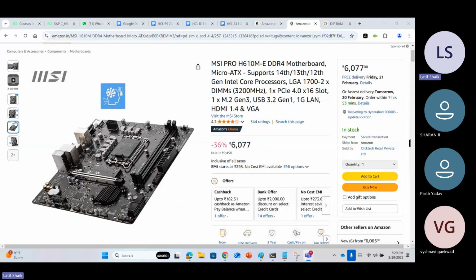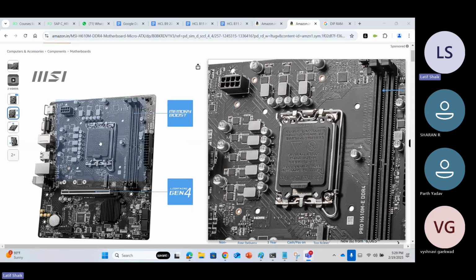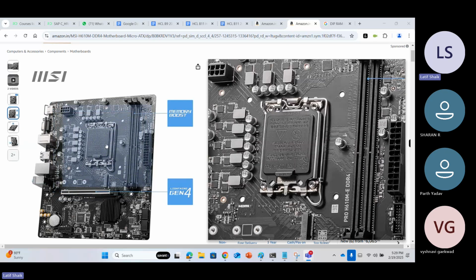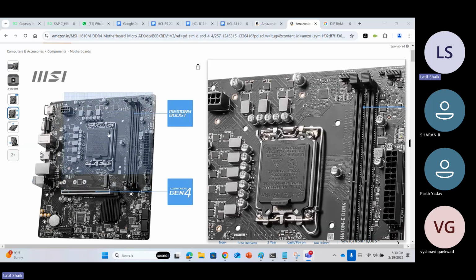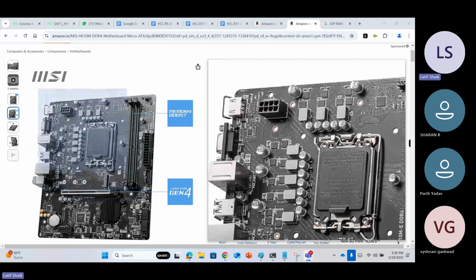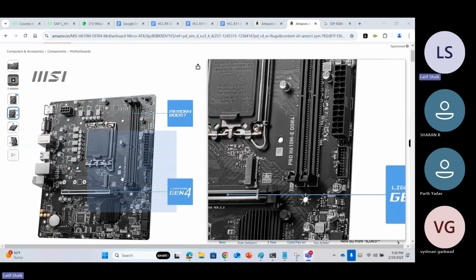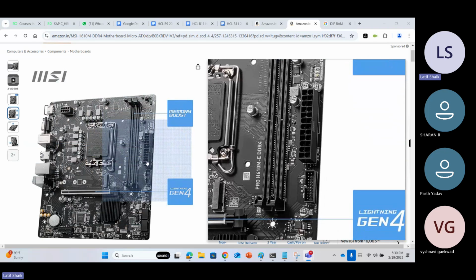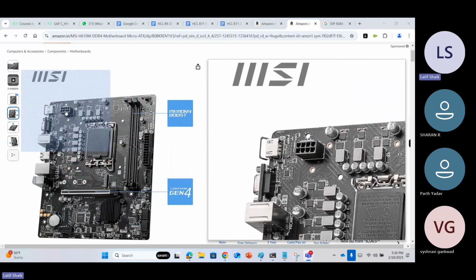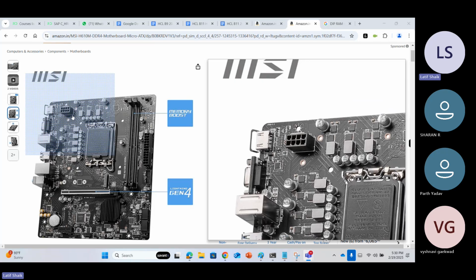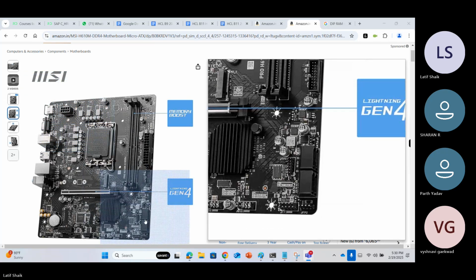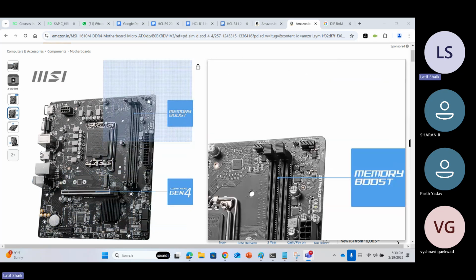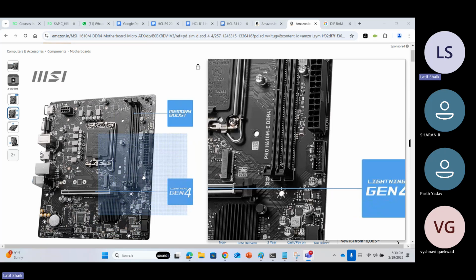See, if you see on the motherboard, some are sockets. Like this, there is no CPU here. So you have to remove this plastic one, okay, and you have to insert the actual CPU inside and lock it, and on it then there is a heat sink. RAM slots you have to insert it. Graphic card you have to insert it. And from SMPS, power supply is connected here. From SMPS power supply, another 8-pin connector comes here. Hard disk will be connected here. Okay, hard disk is connected here. Front panel power on connectors, front panel USB connectors will be connected to these places.